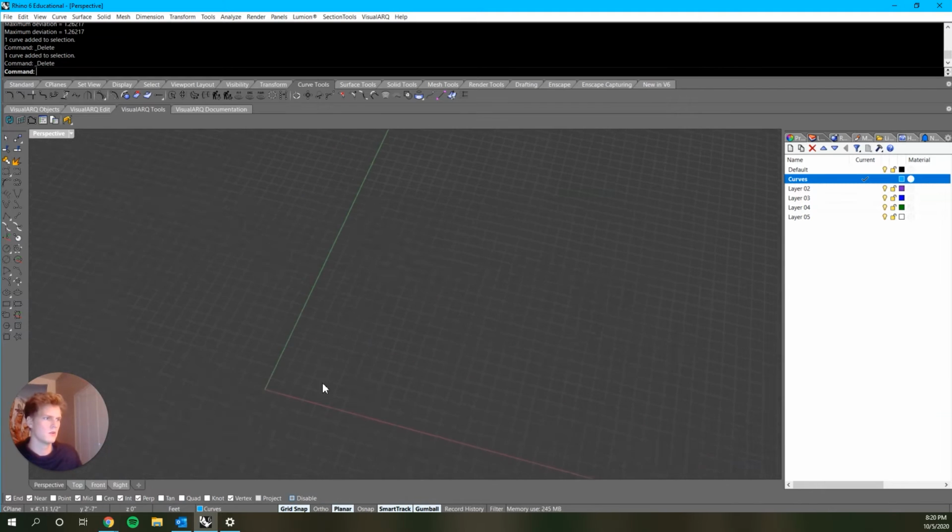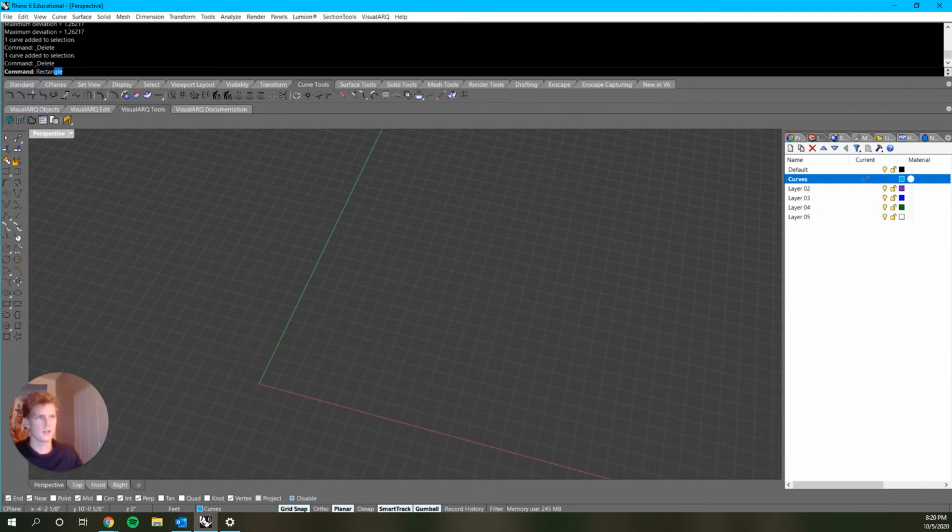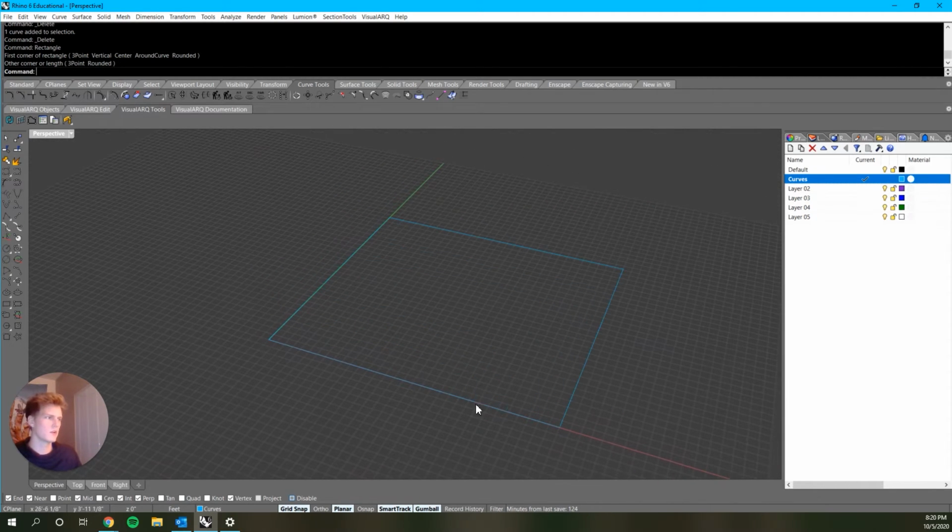Beyond that, we can also make just a rectangle. If you type rectangle, alternatively, they're all over here for more standard shapes. And we can choose 1 point, and then you can either click wherever you want, or you could choose an input value, like let's say 40 feet, enter, by 30 feet. And you'll see this prompts you up at the top every time, right? So it asks for the length and then asks for the width. And you can say 30 feet, and there's your 30 by 40.